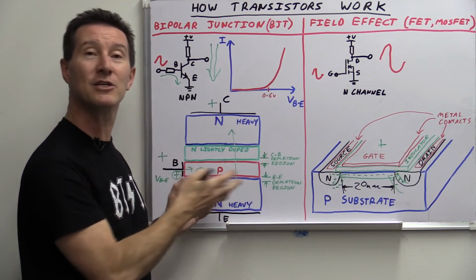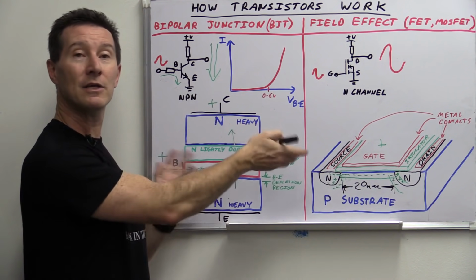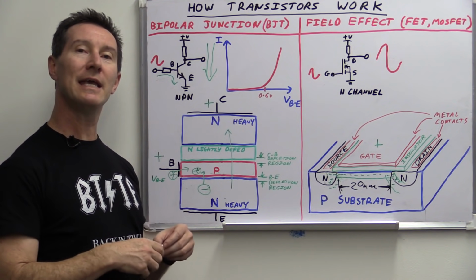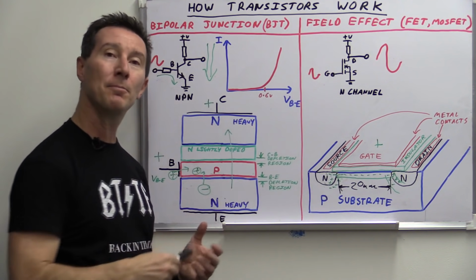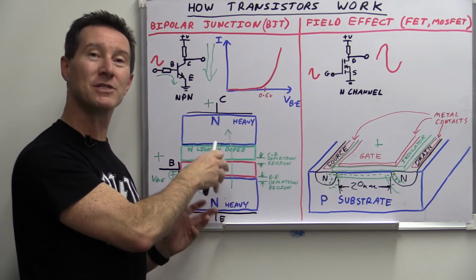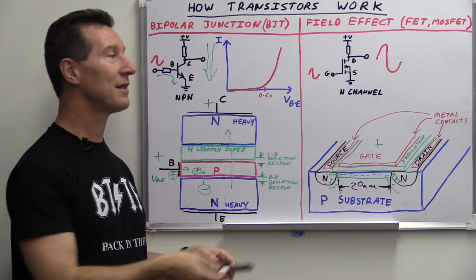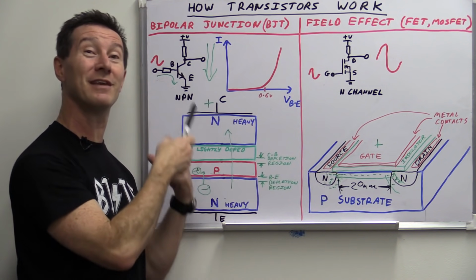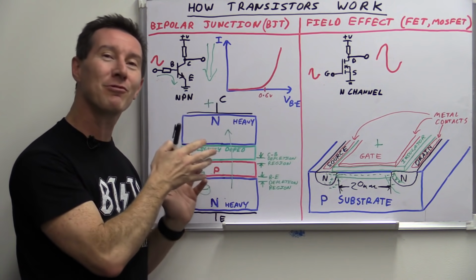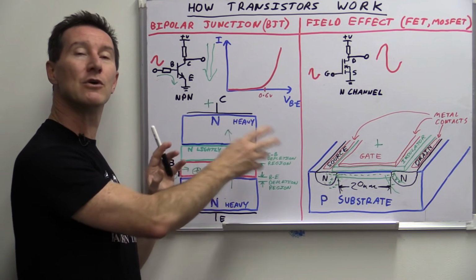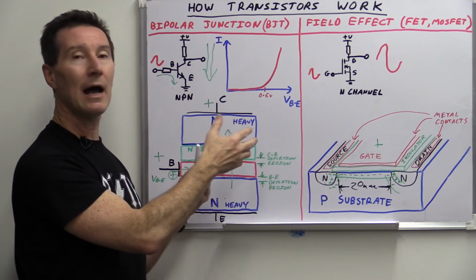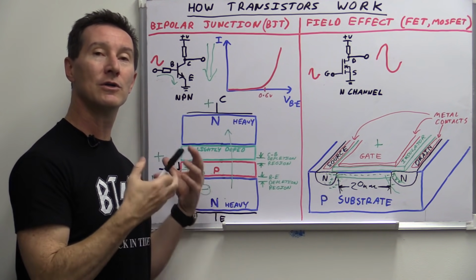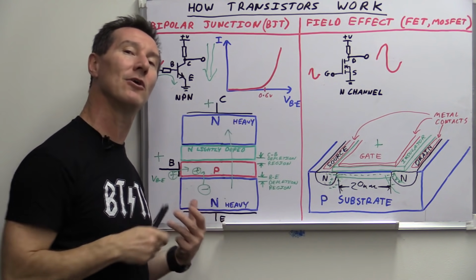If you know this, then you pretty much know how these transistors actually work on the silicon level. And I've only covered NPN and N-channel devices here, but you can think of PNPs and P-channel MOSFETs as being basically the opposite of what's here. It's not quite, they do operate a bit differently. They have negative gate voltages, for example, but JFET N-types can have negative gate voltage as well, and I could probably do a separate video on that. But there are physical differences and also operational and parametric differences between PNPs and P-channel and N-channel devices. But pretty much it's basically the opposite of what we got here.